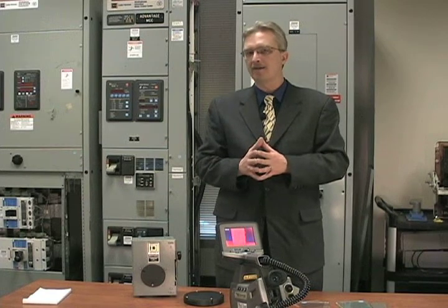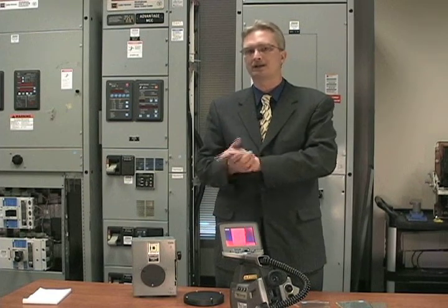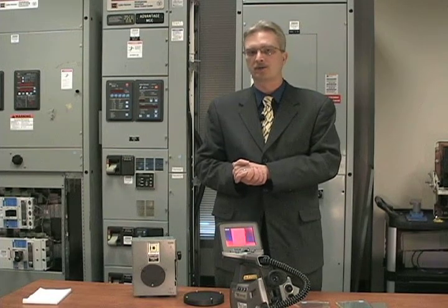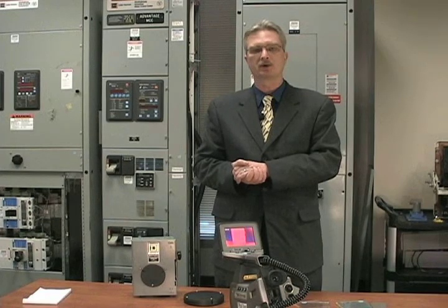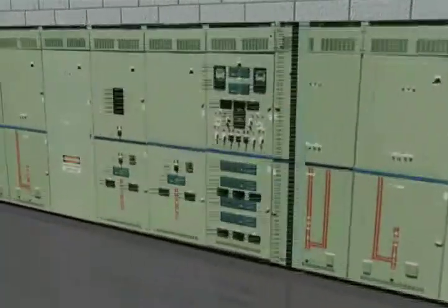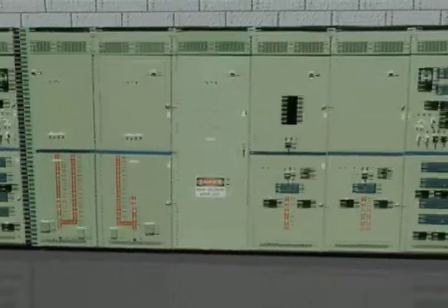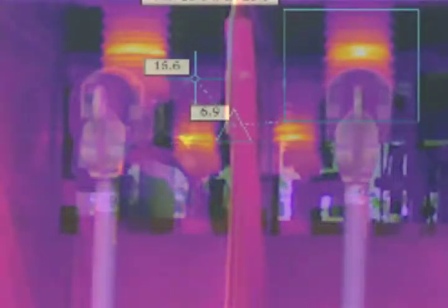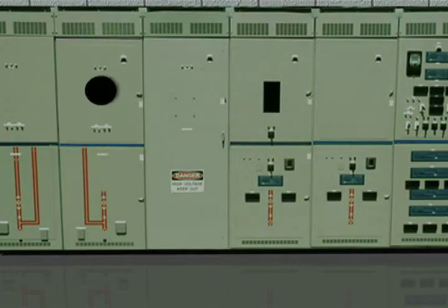And an infrared camera does not have to contact that target to measure the temperatures or see where there's something warmer or colder than it should be. The different applications that we're going to be able to use infrared for, and the applications that it's commonly used for, include energized electrical switchgear. While the switchgear is actually on, we can take an infrared camera, safely open up the switchgear, or use an infrared window to be able to view through it.